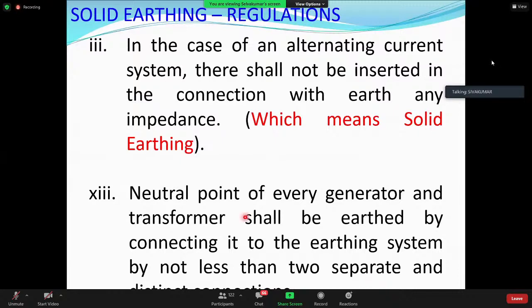So they say, even if you don't invest in ELCB or ELR, an owner will definitely want to invest in protective devices for his equipment. So in solid earthing, even if such devices are provided only for protection of equipment, like a short circuit protective device or overcurrent protective device, it will itself operate, protecting human beings. You remember the connection coming to your house generally comes from a pole. They do not put any ELCB or ELR there. They simply put a fuse. The electricity board people will put a fuse.